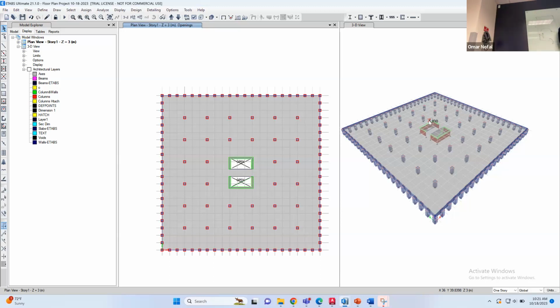If we were able to make this shape here, that means the coupled shear walls are acting with 100% efficiency, but it's impossible to have this efficiency. But how would it look if it's 100% efficient? It's going to be something like this, and this, and it's a line.